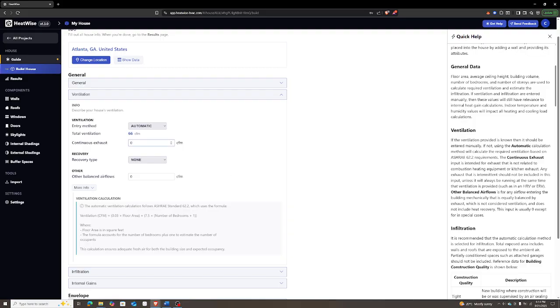And that's the typical house, would not have any exhaust other than intermittent exhaust. For example, bathroom exhaust is turned on and then turned off after a certain time. So that would not be continuous. So we will select or enter 0 for this. It's quite uncommon that this would have a non-zero value, but in case it does, that option is there.